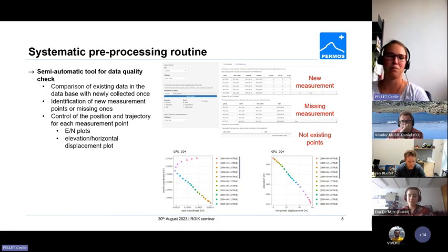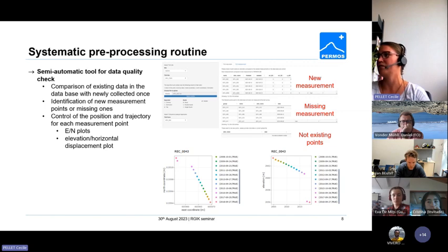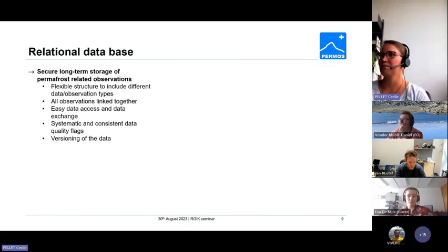In this particular example there is not, but in this one something happened. You have a shift in the trajectory and also a large drop, so probably a boulder turned or fell somewhere on the rock glacier. Then you can flag this data and go on with the processing.